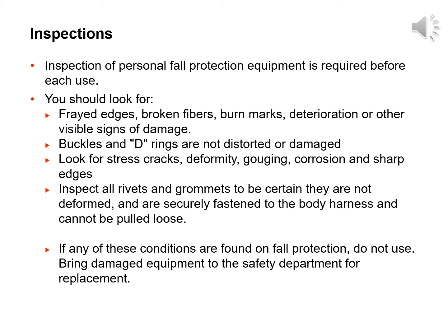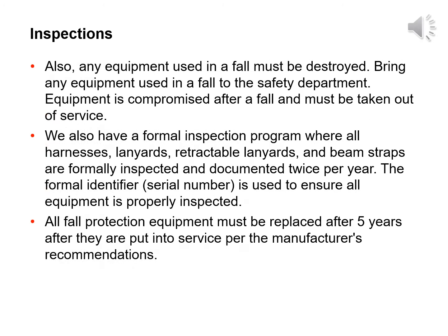If you find any damaged equipment, take it to the safety department for replacement. The safety department must keep record of all destroyed fall protection equipment. Also, any equipment used in a fall must be destroyed. Equipment is compromised after a fall and must be taken out of service.